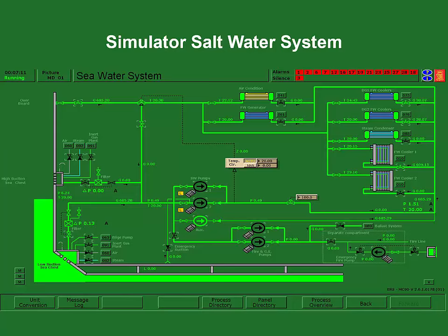So to reduce the amount of maintenance, the saltwater systems now are as small as possible. The reason there is a lot more maintenance is the cleaning of the heat exchangers and supply lines to remove marine organisms, and the replacement of sacrificial anodes to protect the heat exchangers and the lines from galvanic corrosion. So you had a lot of repairs to corrosion and also removal of the marine organisms.